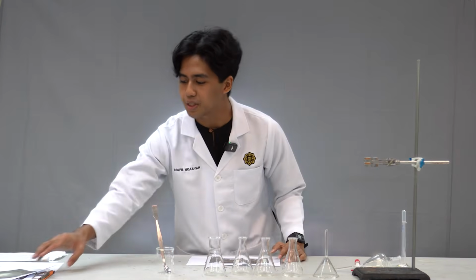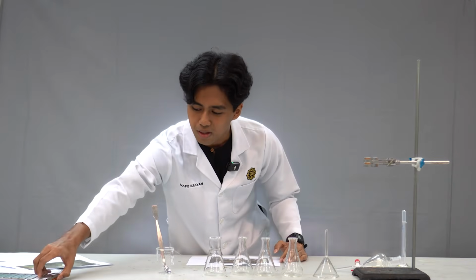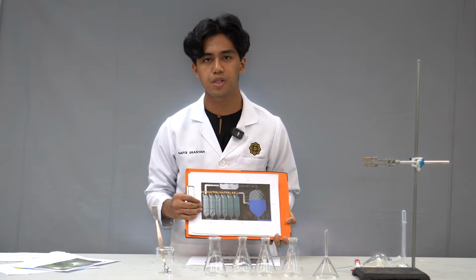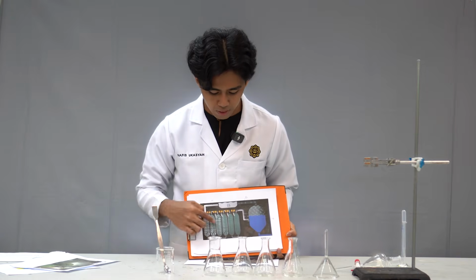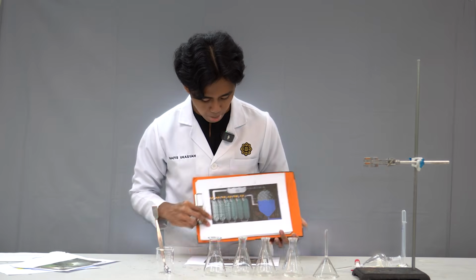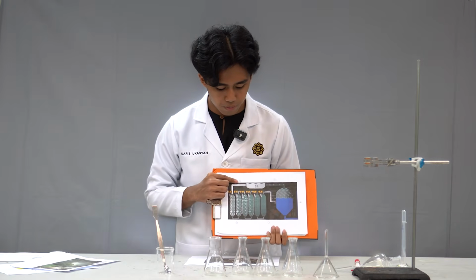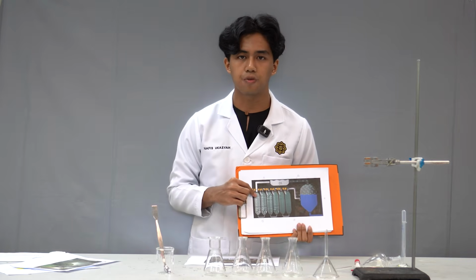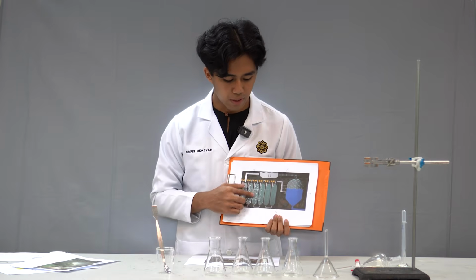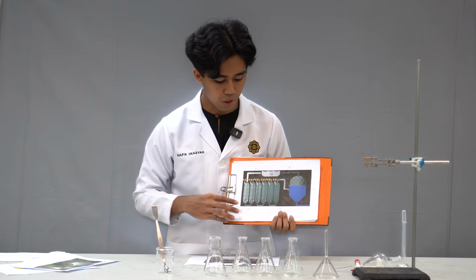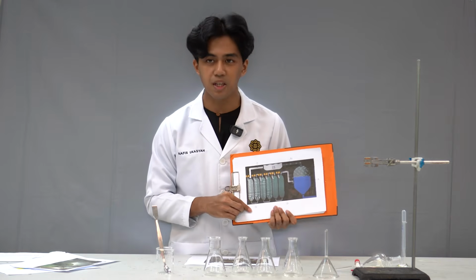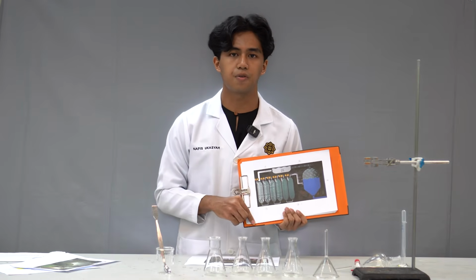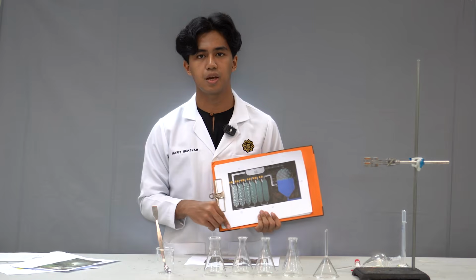So the next step is where the extraction process happens. The extraction process happens when there are 6 tanks connected to each other. For the first point, liquid CO2 will be pumped to the tank to pass through the coffee bean, tank by tank until the last tank. In the tank, the liquid CO2 is a very selective solvent. So it will dissolve the caffeine but not other flavor and aroma compounds such as acid and oil.